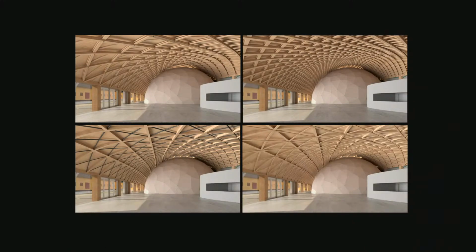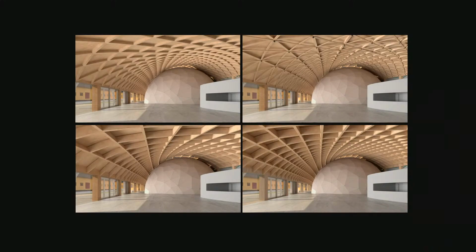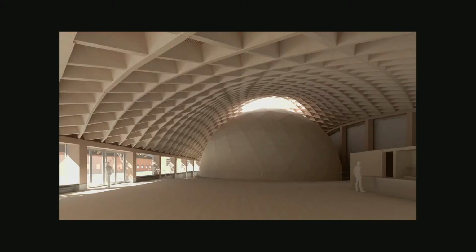So in the following process, where we had to balance economy, technical, and aesthetic points of view, we had some difficulties with the fire requirements. We started to look for alternative concepts, and at some point we were quite desperate and also introduced steel bracing. But in the end, it turned out to be a quite interesting shift to a new type of structure, one could call it a timber lamella roof system with LVL members, and then there was still a shell of LVL on top of it.